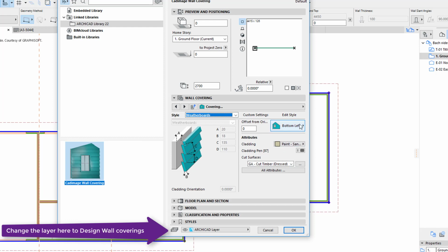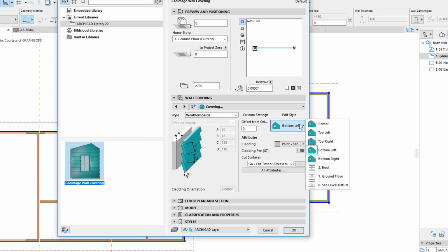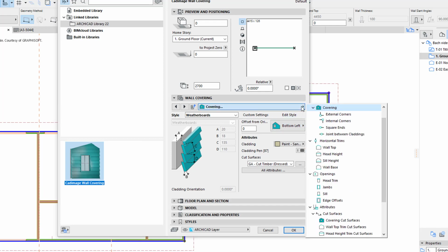There's a few that we will change later on when you're going to do things like the wall height, head height, and openings. But openings, we'll just leave the default ones because normally Archicad does a good job of detecting where the windows are.